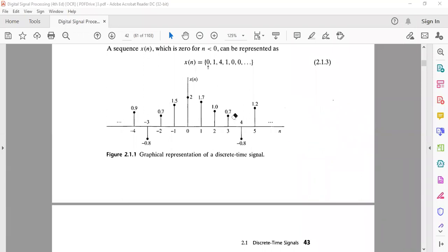So you can represent your discrete signal this way, graphically. This is the graphical representation of a discrete signal. We have x[n], the amplitude of your function, and this is n, the sample period. If one was going to take a wild guess, you could probably think that your sampled signal was something like this.